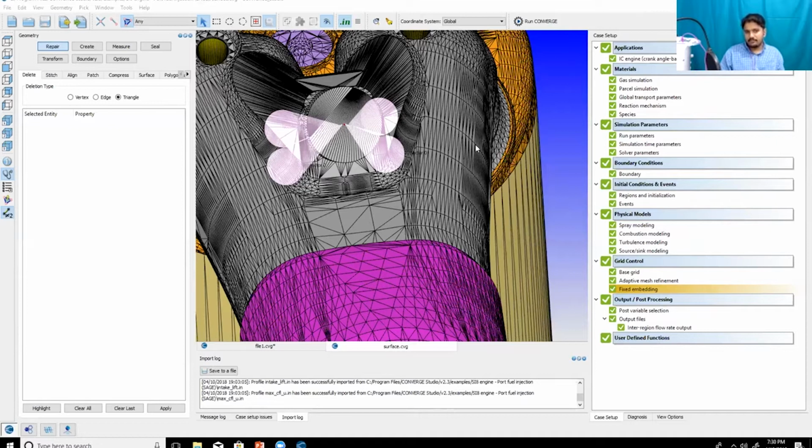Nitin, if you use Converge, then I'm pretty sure you're familiar with AMR, right? Adaptive Mesh Refinement. So the AMR is a very standard parameter, and there is something called the subgrid scale parameter, right? There's a velocity parameter and the temperature parameter. I would change that, and that will actually help you out.